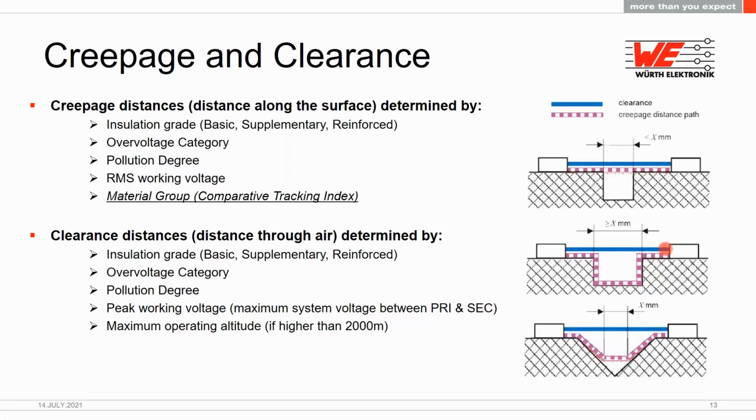In some cases, the standards may have special requirements for the length of the gap that must be maintained in order for the creepage path to follow the insulating material. This is why you see in this top figure, the creepage path actually jumps across this gap, because this gap length is not long enough to be counted according to this particular safety standard.